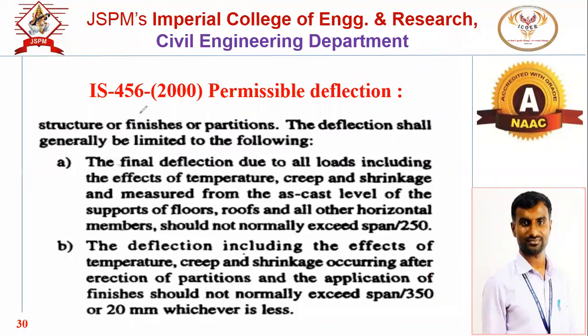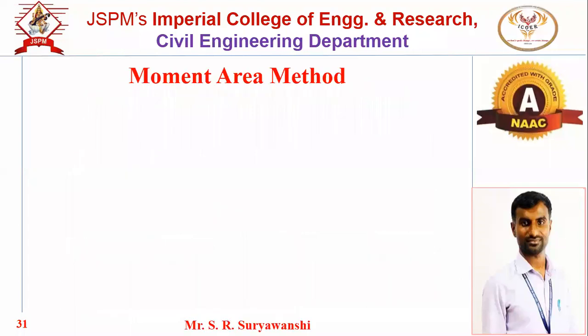These clauses you have to study in detail in your SD2 subject. Right now you remember L by 350 or 20 mm, whichever is less, and final deflection is L by 250. It is more than sufficient. You may expect one MCQ based on the permissible values. Okay. Now we will start with the moment area method.